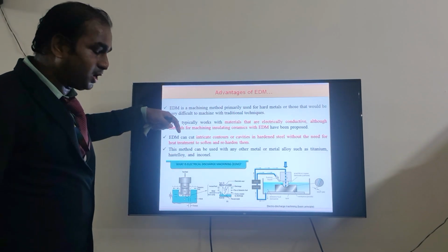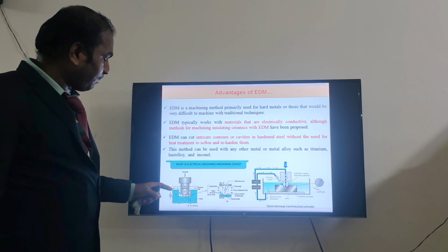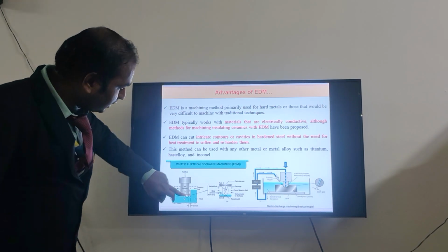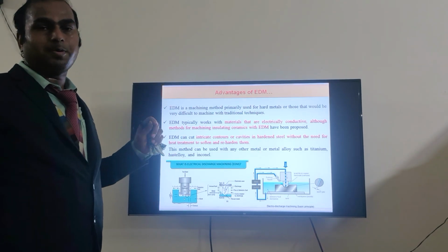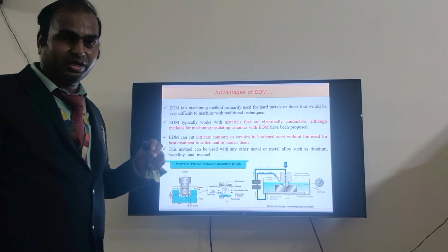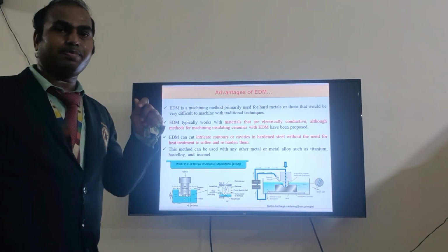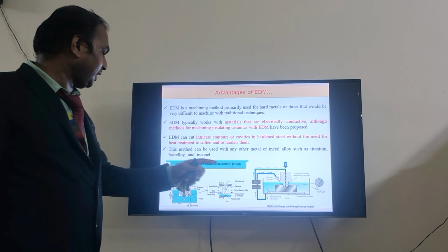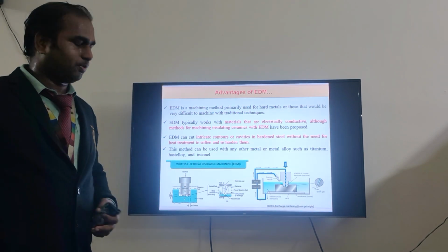When the tool is fed in the vertical direction, the gap between the tool and the workpiece, with the help of a dielectric medium, lets very small debris be flushed out when the dielectric medium is concentrated with high-pressure fluid. Normally this method can be used on super metals and super alloys like titanium, Astroloy, Inconel 625 and other hardened workpiece materials.